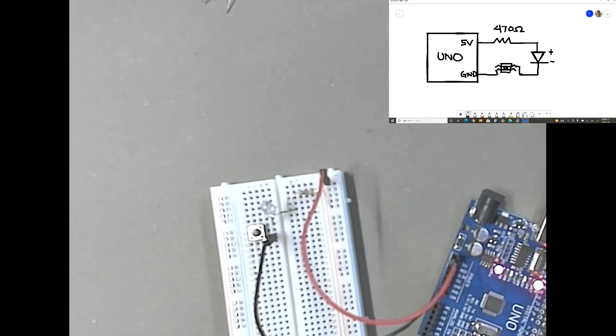All right, so let's go ahead and take it another step, kind of combining some of the things that we've learned. So going back to our schematic, let's add two lights. To add, what we need to do is always just put the other light using the same connections as the first light.